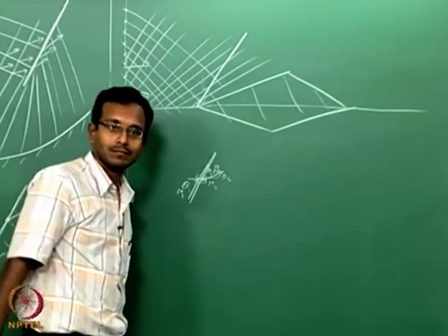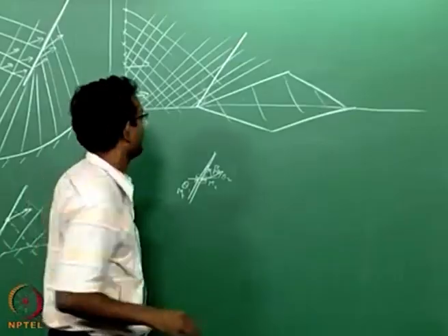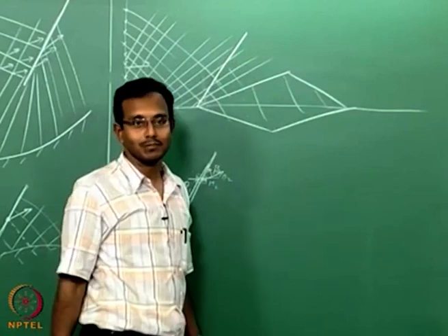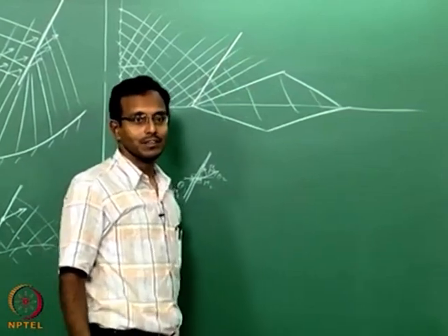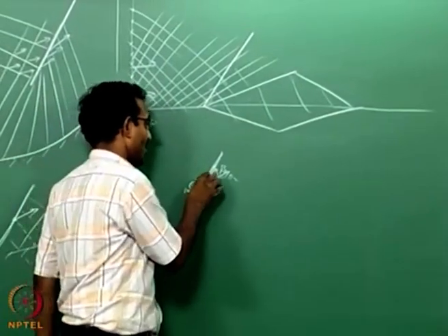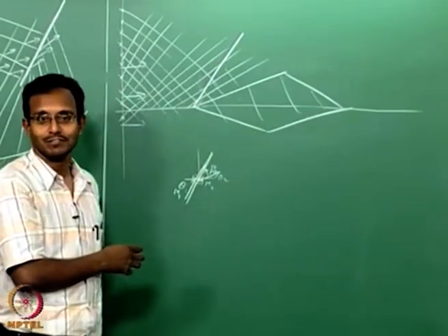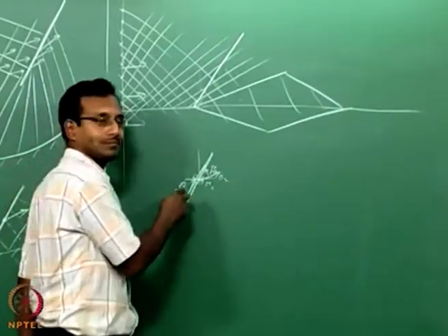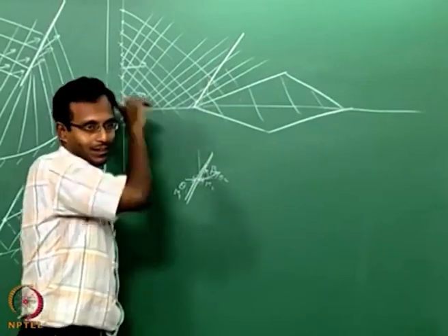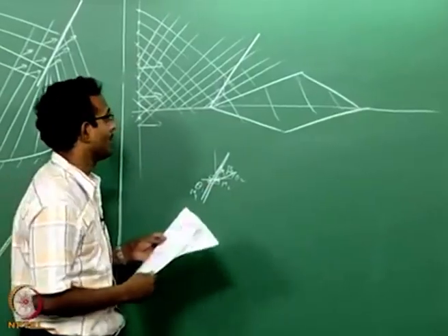This is what I will get. Once I get this, as long as M2 is supersonic, I can still use the method of characteristics. I can still say I will have characteristics running this way and I can start solving the problem. That is what we will be doing, except there will be cases where the characteristic on this side will run up. If it runs up this way, you cannot solve it. You will have this problem. When this happens, some characteristics will be lost, only some will be useful. Only the right running characteristic will be useful, left running characteristics will become useless. That also can happen in this case.